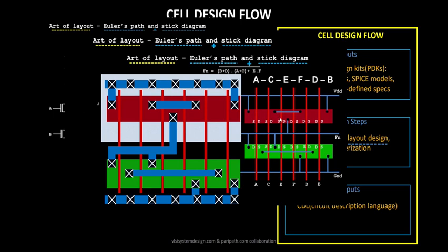In this case, for example, if you look at the E input of this transistor, this represents your NMOS, this represents your PMOS, and this is source, this is drain. It says your E transistor source and C transistor drain are connected, and your F transistor source and your D transistor drain are connected. Basically the PMOS transistors' source and drain are connected, and this particular block means your A transistor source and your C transistor source are connected. That's why you see your contact over here, and this in turn is connected to your D NMOS transistor drain and the B NMOS transistor drain.